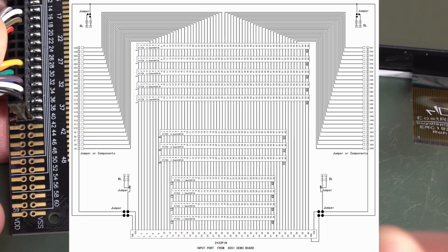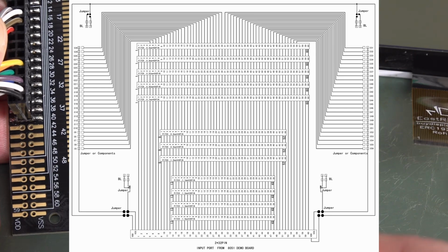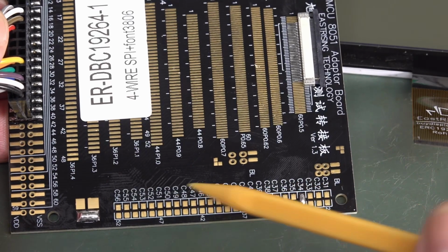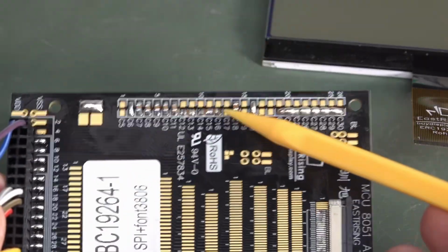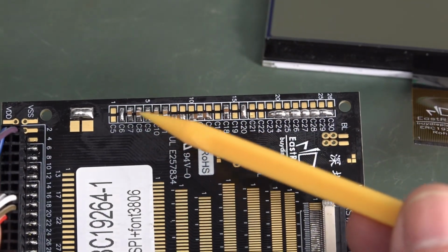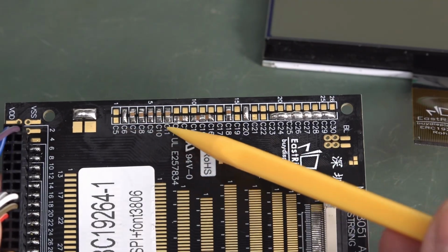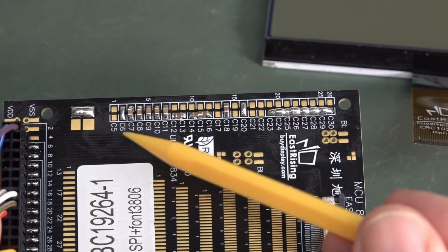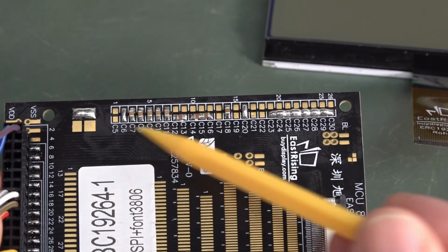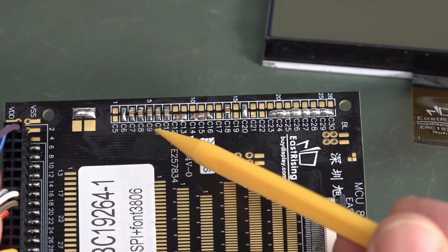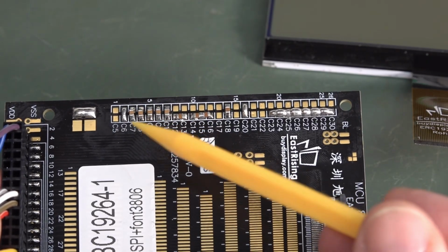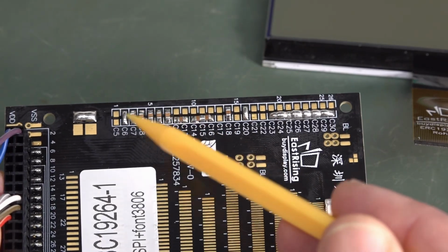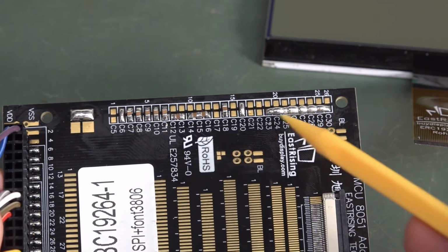I think this is like the positive side. They should label it a bit better, but anyway, you can tie each individual pin down to ground up here. So they've installed some caps up here, so you can put capacitors down to ground. They would be for the internal contrast boost converters, for example, the bias capacitors, the bias pins on the LCD. So you have to put those in various configurations. Yeah, they've got a capacitor across 2 pins there, or they've got others going down to ground like this, and they've strapped these pins here.